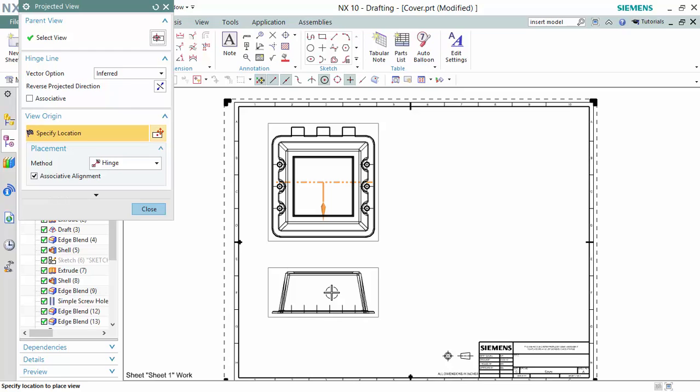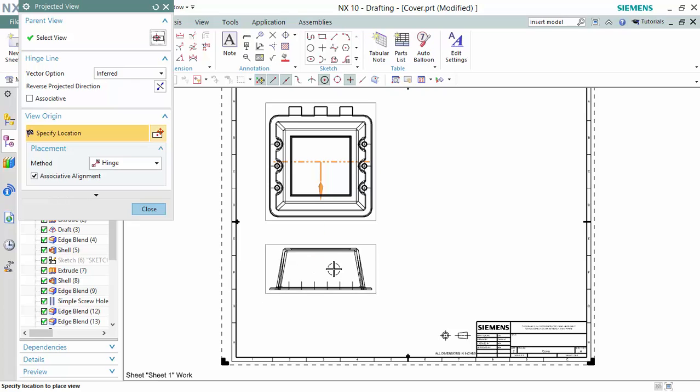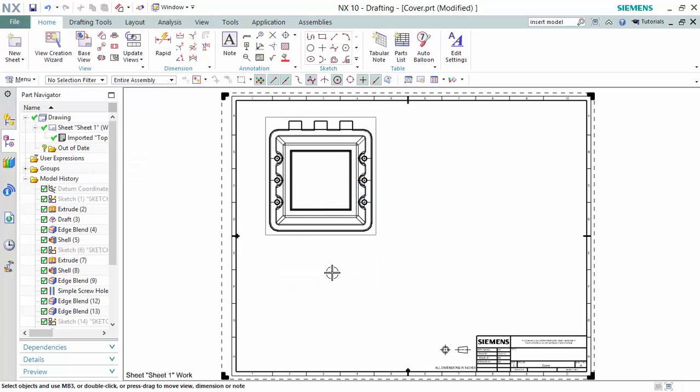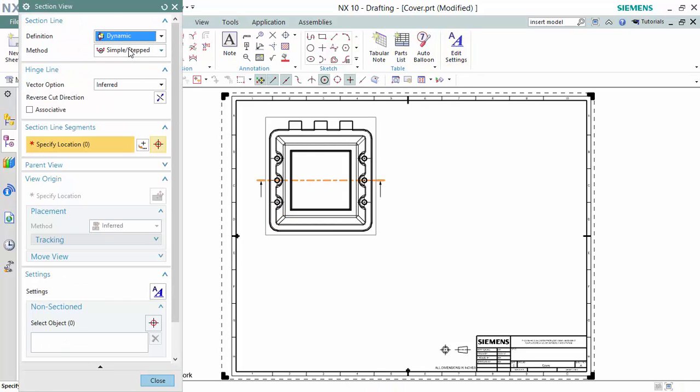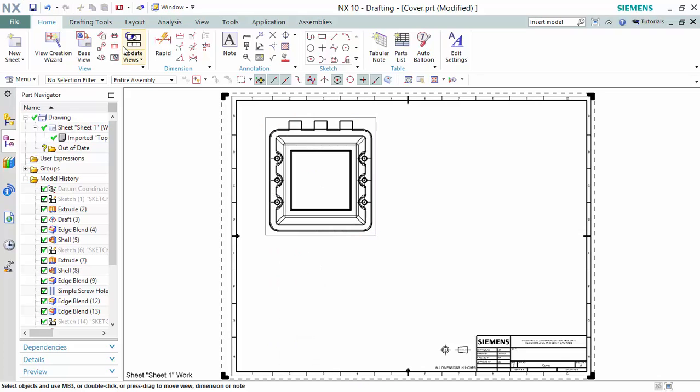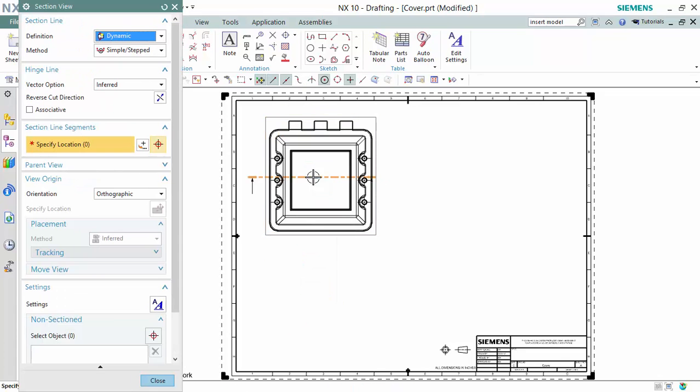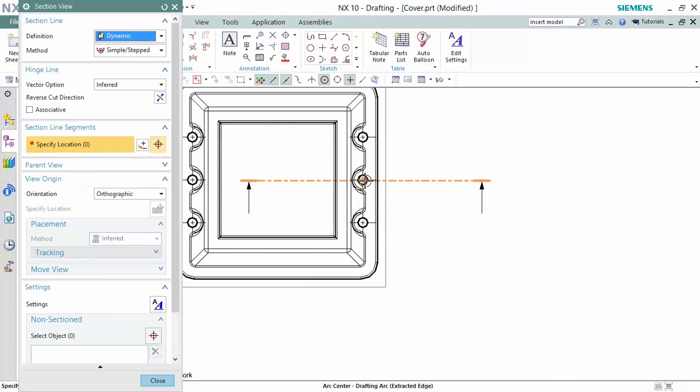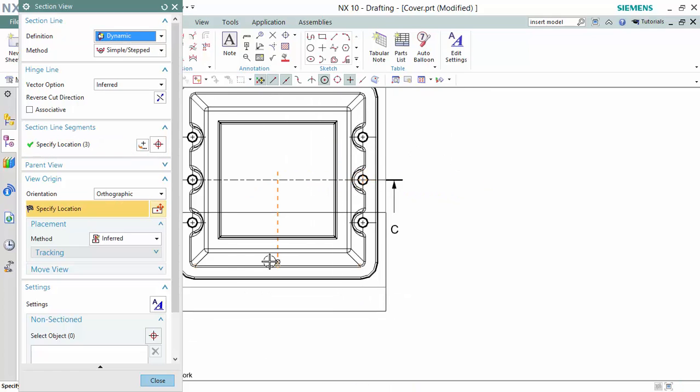Usually for basic isometric drafting drawing, you would use a top, front, and a right view of the component, but to save as much space and make it as efficient as possible, we will realize intuitively that this is the front view and it's the exact same as the right view, so there's not really any information we can get from that. So we will actually be creating a section view. You can go to the button here, or you can click on the view, right click it, and say add section view. From here you will want to center it approximately right to the middle.